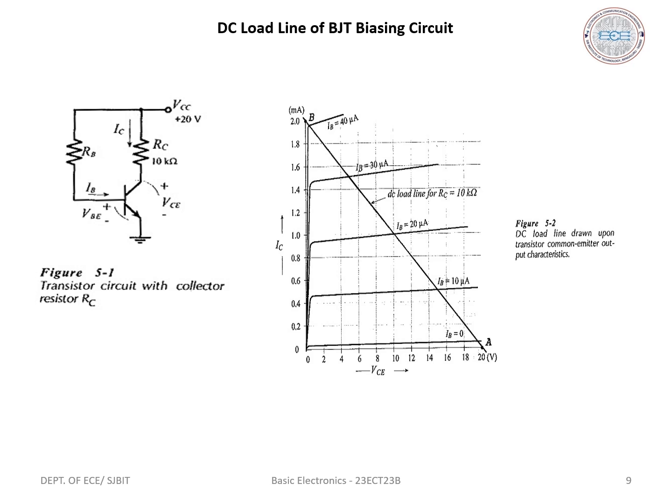Consider an NPN transistor in CE configuration biased in active region. The DC supply voltage VCC forward biases the base emitter junction and reverse biases the collector base junction. So from this, we get the equation IC equals minus 1 by RC into VCE plus VCC by RC, which is similar to the equation representing a straight line, y equals mx plus c. By comparison, it is noted that along the y-axis we have IC and along the x-axis we have VCE, with slope of the line m equals minus 1 by RC.